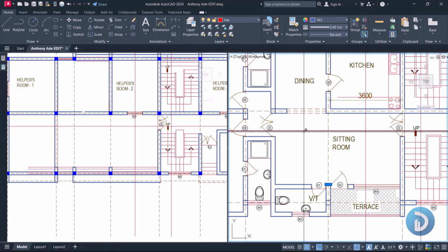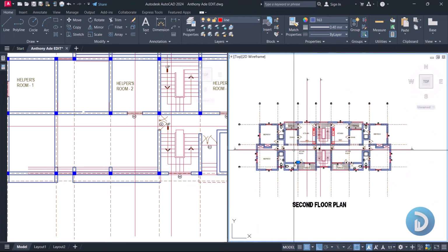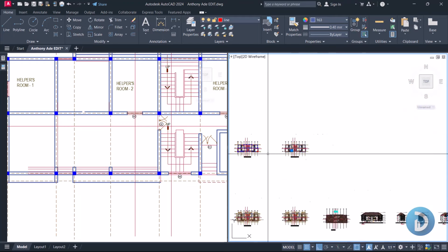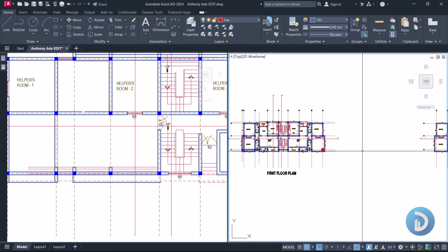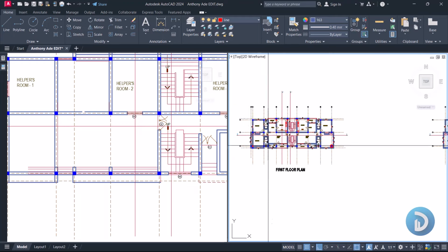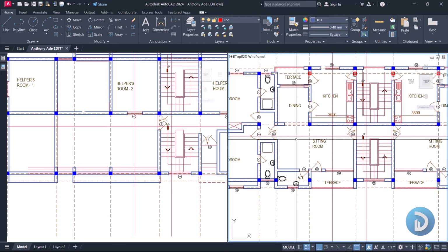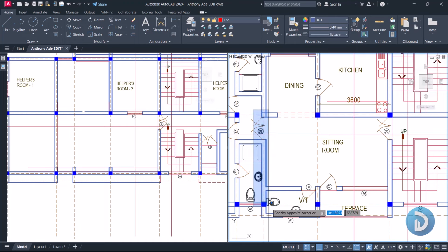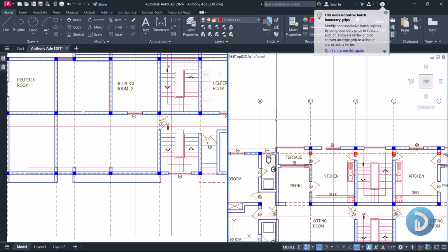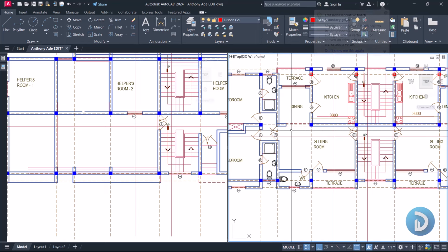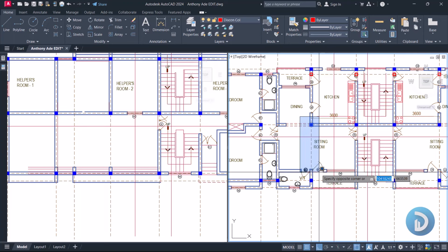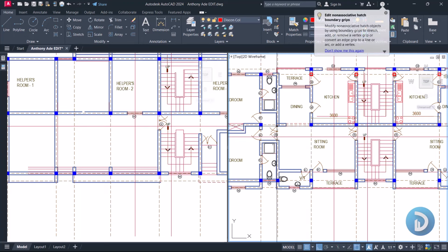But on getting to the first floor, while we are making arrangements to receive the slab that will carry the second floor, we must, or we possibly have to, run a beam on this very grid, which is our B asterisk. We have to run that beam here, so as not to have this beam running on this other grid. So this can now serve from this point to this point as one panel.